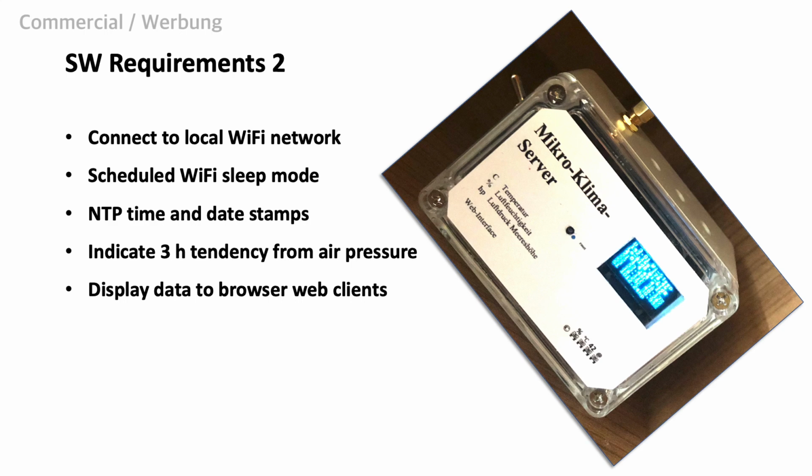Since we want to log our data over the whole year, we need a precise time base. Our board cannot manage this. However, since we are connected to Wi-Fi, we can get time and date from Internet NTP servers. This is even for free, as long as we have only a few requests per hour.